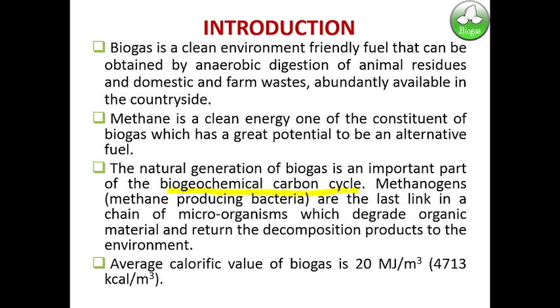Inside, the manure is decomposed into carbon dioxide and methane gas with the help of the methanogenic bacteria. The gas evolves in bubble form and is stored in the upper part of the tank. This is the gas tank. After the conversion, the slurry fills the lower part of the digester tank.